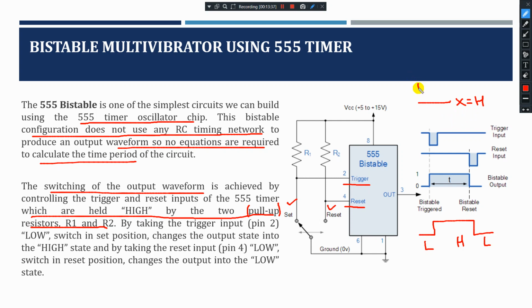So what I can do is connect one resistor here, connect this wire to plus VCC, and have a switch to the ground. Until your switch is in off condition, your X value will be high, that is equal to VCC. When the switch is closed, the current flows through the easiest or least resistance path, then your output goes to 0. So this is called a pull-up resistor.